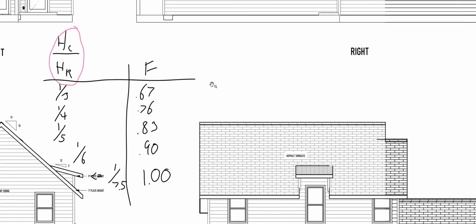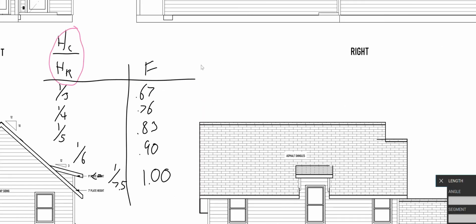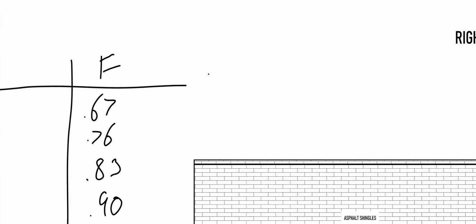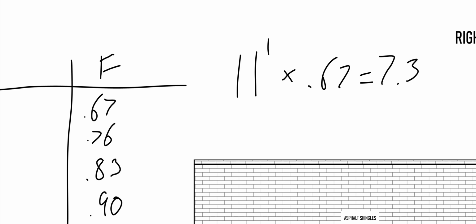All right. So we know that when those rafters are being loaded like that, we take the allowed 11-foot span from the table, if we want to use 2x6s, multiply it by 0.67, and our new allowed span is 7.37 feet, okay?